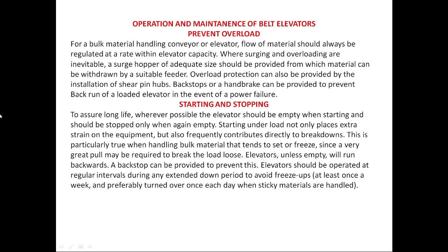Elevators, unless empty, will run backwards. The backstop can be provided to prevent this. Elevators should be operated at regular intervals during any extended down period to avoid freeze-ups, at least once a week, or preferably turned over once each day when sticky materials are handled.